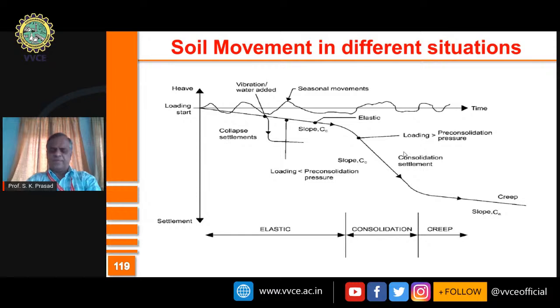So basically, fundamental elastic properties like Young's modulus and Poisson's ratio play a role. Naturally, soil which has more Young's modulus shows stiffer behavior, so settlement is less. On the other hand, with lower stiffness, automatically settlement is going to be more. And it is the consolidation settlement which is predominantly causing settlement. Not all soils experience consolidation settlement. It's basically the clayey soils which experience consolidation settlement.